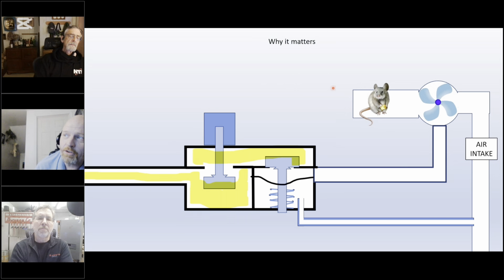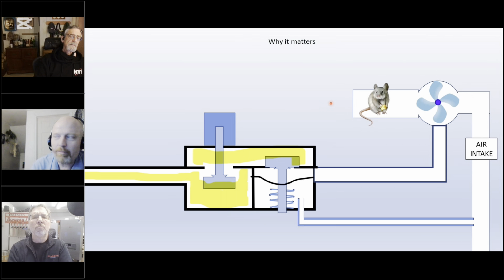On the exhaust side, you can use the exhaust test port on the boiler and do the exact same thing. Take 2 or 3 inches of manometer tubing, shove it into the exhaust test port, run the boiler at its maximum firing rate. And again, typical back pressure on 3-inch venting is going to be maybe up to 1/2 inch.